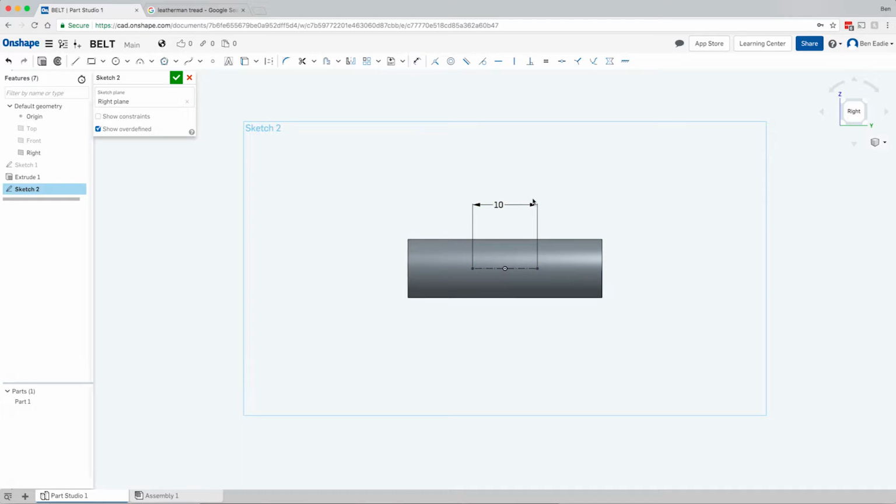So we've got that set up, and now there's a couple of different ways we can deal with drawing that hex area. We can come in and draw out standard lines. One neat thing about lines is that you'll notice this highlighted to the origin. I was kind of off to the side of the origin, and it goes, hey, wait, you probably want that to be related to that. So it'll make sure that that point is always horizontal to the origin. I can click down and drag out the other line, and I'll just sketch this out.